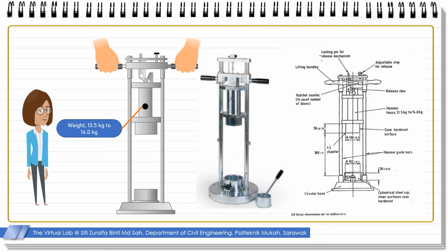The standard amount of impact is produced by a known weight, that is a steel cylinder, falling a set height, a prescribed number of times, onto an amount of aggregate of standard size and weight retained in a mold. Aggregate impact values, AIVs, below 10 are regarded as strong, and AIVs above 35 would normally be regarded as too weak for use in road surfaces. Aggregate impact values and aggregate crushing values are often numerically very similar, and indicate similar aggregate strength properties.